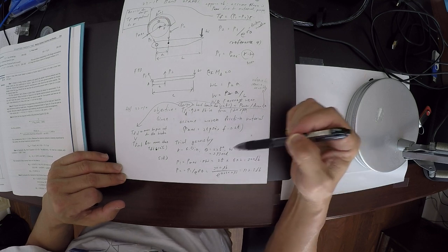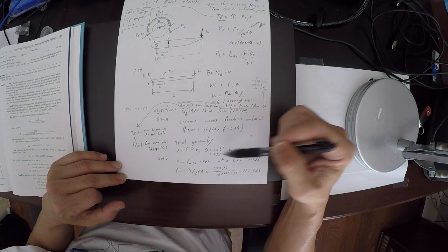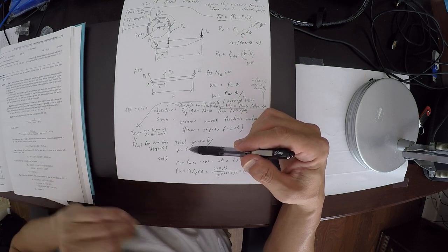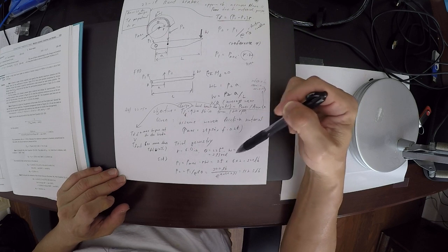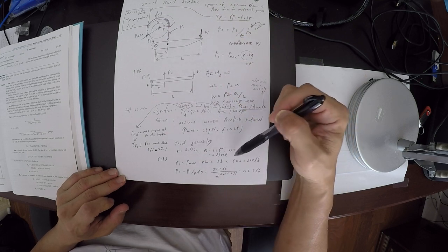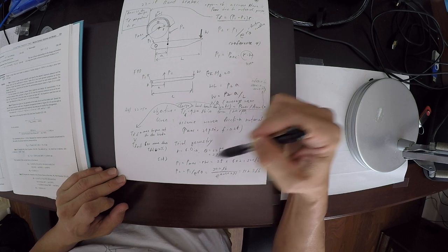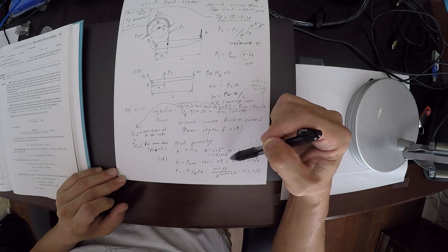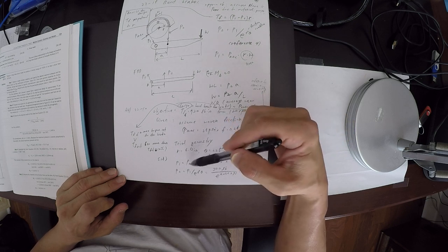Okay, so this is a triangle geometry, so you need to figure out some numbers for the R, which is the radius of the band drum, and then theta, the coverage of the brake pad, and then the W, the width of the brake pad. So once you have this prepared, the first thing, again, is that you try to find P1, because we have the P max pressure given.